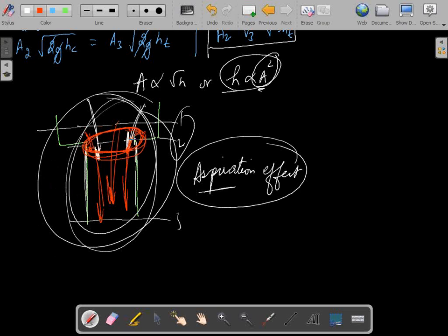So I'm just giving you a hint, you'll have a negative pressure head at section 2. You will have air inclusions at section 2, which will not allow it to flow further. But instead of a cylindrical thing, if you create a tapering section, what will happen?